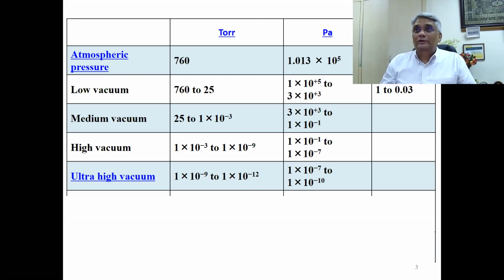You don't want the presence of any extraneous gases inside the system. So the vacuum levels in such analytical tools start at 10 raised to -9 torr, right? These are huge chambers. As the chamber size increases, the complexity of getting and maintaining high vacuum levels also increases. So that is ultra high vacuum.